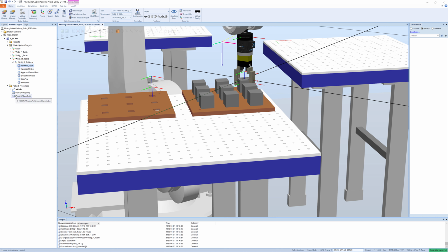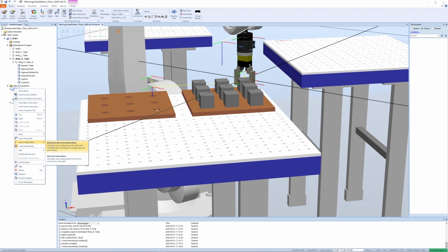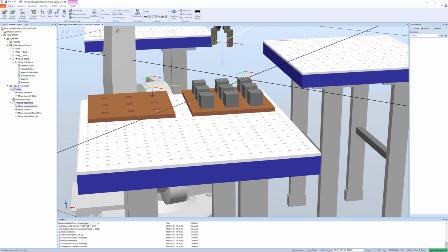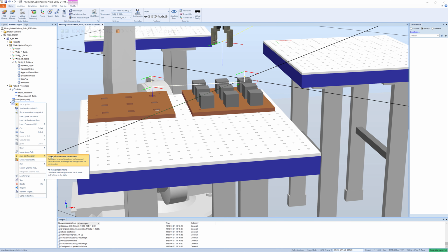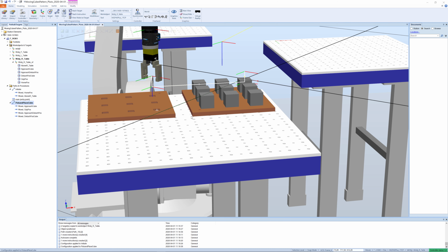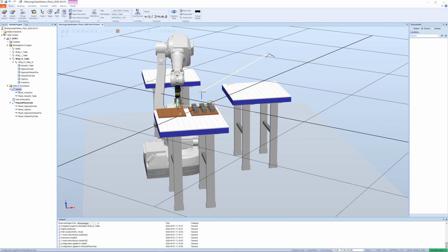That's fine. And in the pick and place, we go to the approach cube and grip pose, and then approach detach pose and detach pose cube. This one. And then to be sure that everything works, we do the auto configuration, right click, make an auto configuration, and then check that it is able to do the motions, move it on path.